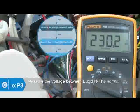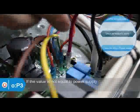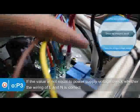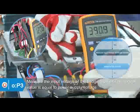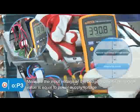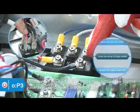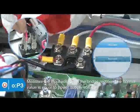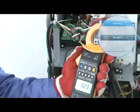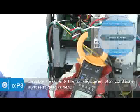Measure whether the voltage between L and N is normal. If the value is not equal to power supply voltage, check whether the wiring of L and N is normal. Measure whether the input voltage of bridge rectifier is normal. If the value is not equal to the power supply voltage, check whether the wiring of bridge rectifier is correct. If the wiring is correct, measure whether the current is normal.